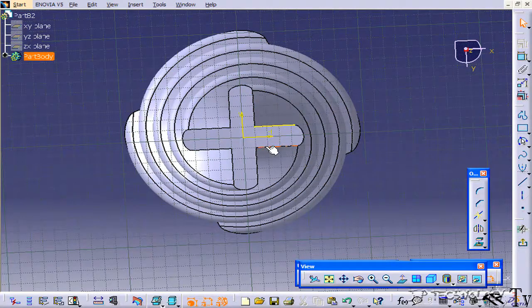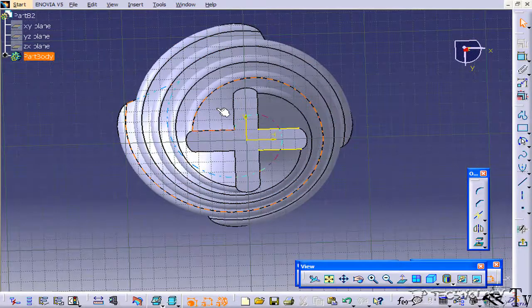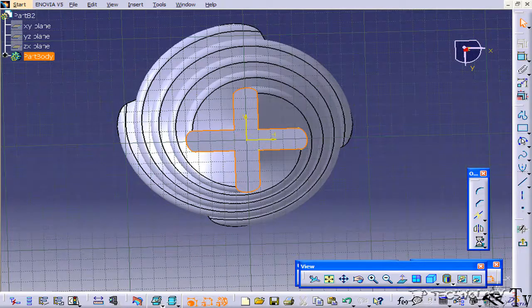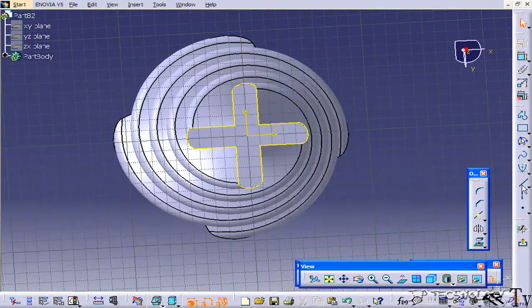Now, it can also work the other way. You can click a line, and you can click Project, and it'll be projected. You're also able to click on, say, a whole face. So let's click this face, click Project, and we projected all the lines touching that face. Now, if we go again with our line tool, we're able to snap onto all of these points.